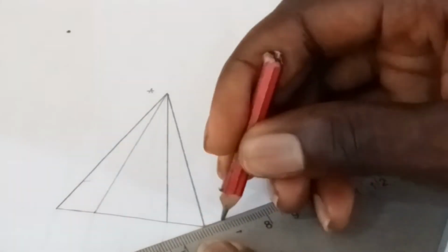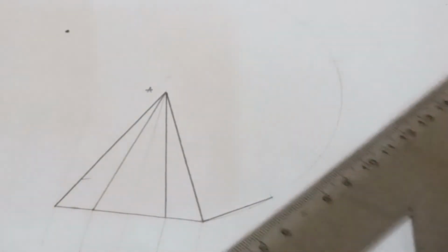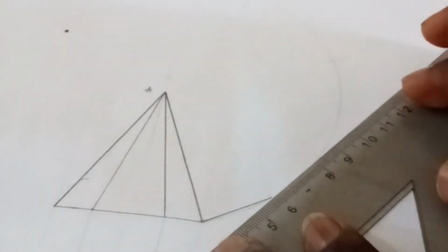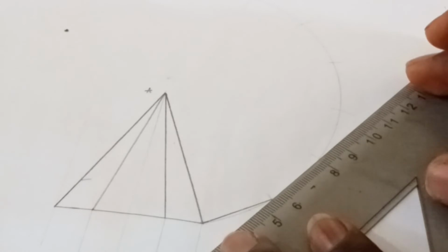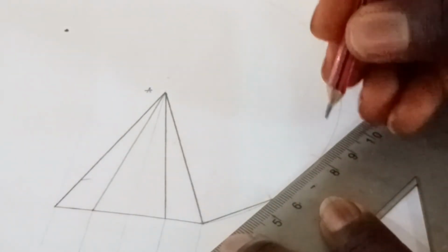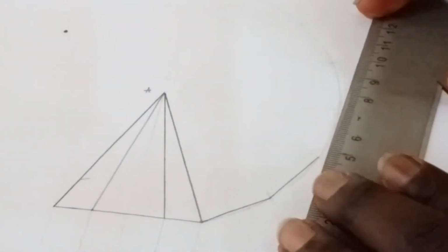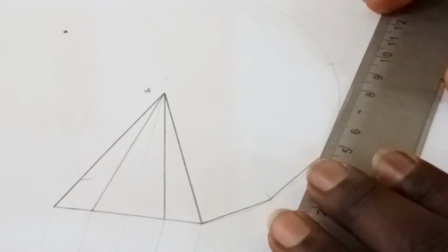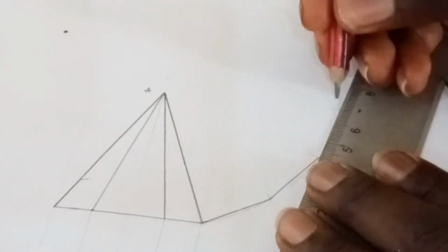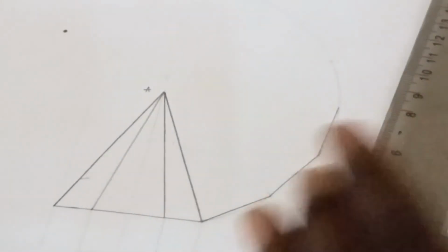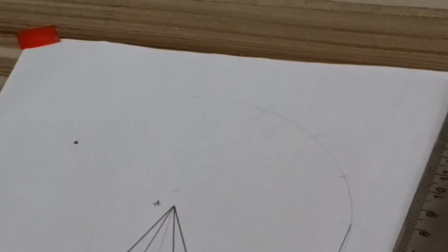Nice and easy. So we have to draw short horizontal lines to join each of the arcs we've cut, but starting from the base of the triangle, right? So draw a horizontal line from the base of the triangle to the first arc. Next, from the first arc to the second arc, draw a horizontal line with thick continuous lines, because this is part of the development we want to draw. So you do that for all 6 arcs.